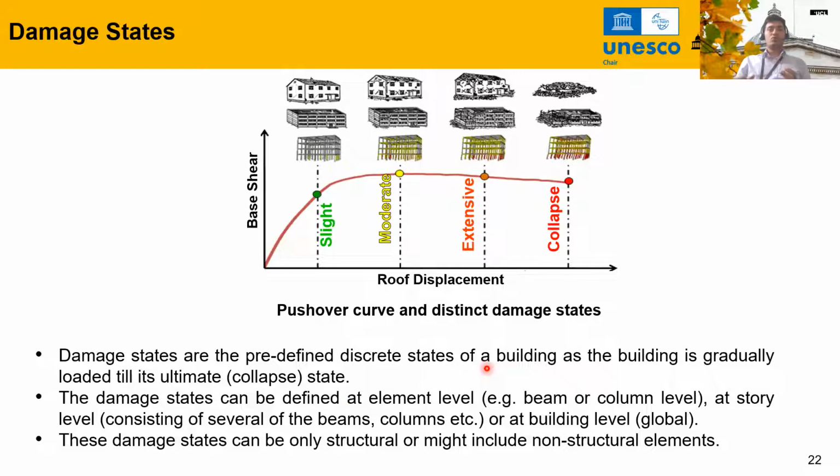Now, after you get the Pushover curve by doing the Pushover analysis, we also need to define the different damage scales and damage states along your Pushover curve, because after you do the pushover analysis, you already have the idea of, okay, when does the collapse occur? So you did your pushover analysis up to the collapse point. So this is the collapse state.